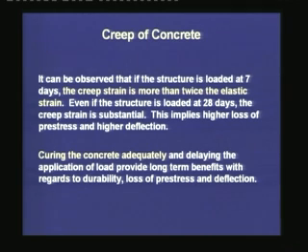In pre-tension plants, there can be pressure to produce the pre-tension members quickly and transfer the pre-stress quickly so as to clear the pre-stressing bed. But it is always advisable to delay the transfer of pre-stress so as to reduce creep. Let the concrete have proper hydration, and then we can expect better performance of the concrete member with increased durability and reduced deflection.